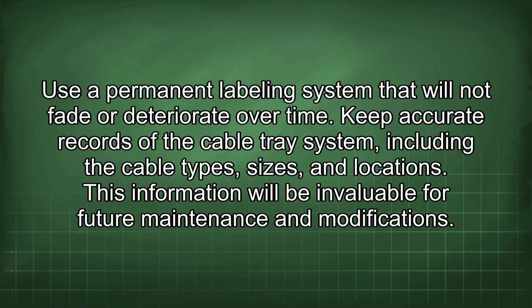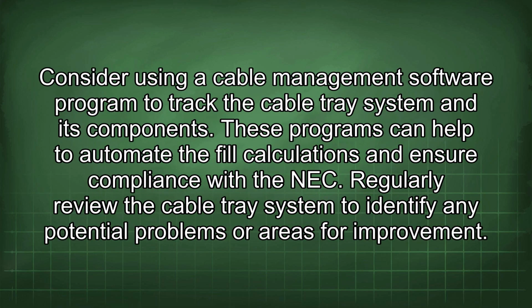Keep accurate records of the cable tray system, including the cable types, sizes, and locations. This information will be invaluable for future maintenance and modifications. Consider using a cable management software program to track the cable tray system and its components. These programs can help to automate the fill calculations and ensure compliance with the NEC.